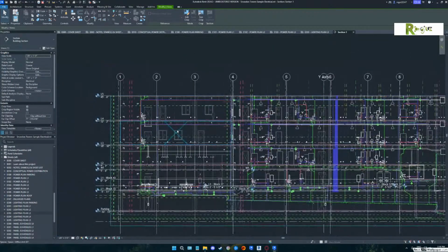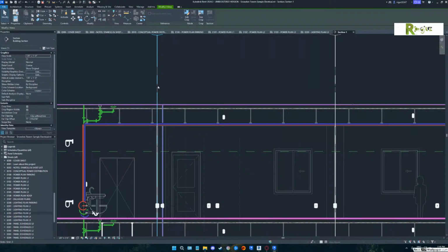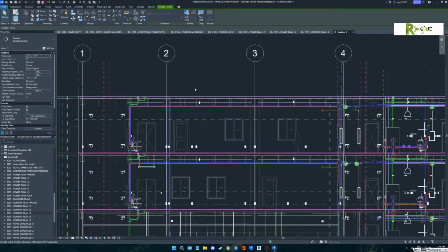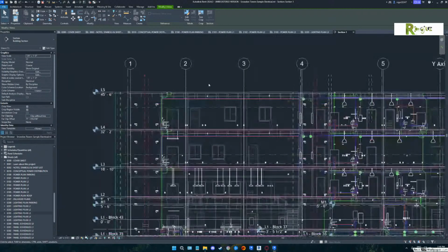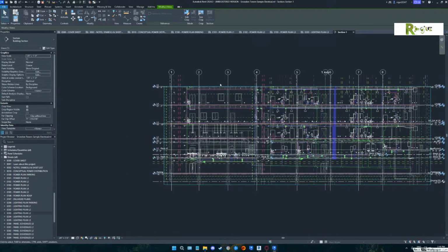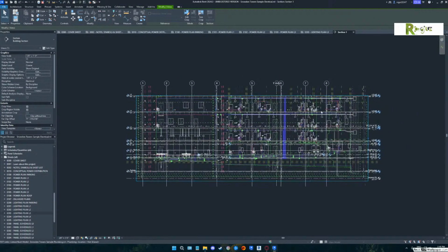What break lines are you talking about? When you look at the column line, it should be a line, a gap, a dash, a gap. Right. But because none of those line up, you have so much overlap that it appears as one line. Right. Those center line styles are all on top of each other, and thus making the line style look like it's a solid line. Oh, okay, I see. Bad practice. And the same thing's happening with the level lines too. The exact same thing's happening with the level line.